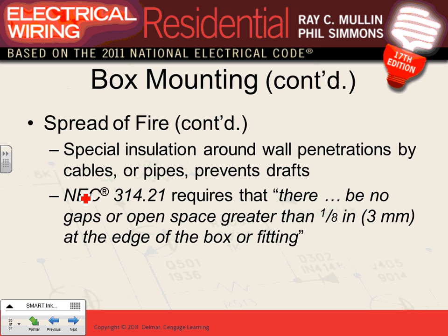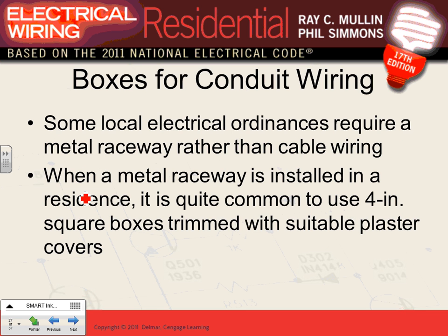We talked about the no gap. Because of the spread of fire, guys, you don't want to have a gap less than required. There will be no gap or open space greater than 1/8 inch at the edge of the box or the fittings. Again, it's all about the spread of fire, so you're going to close all these.